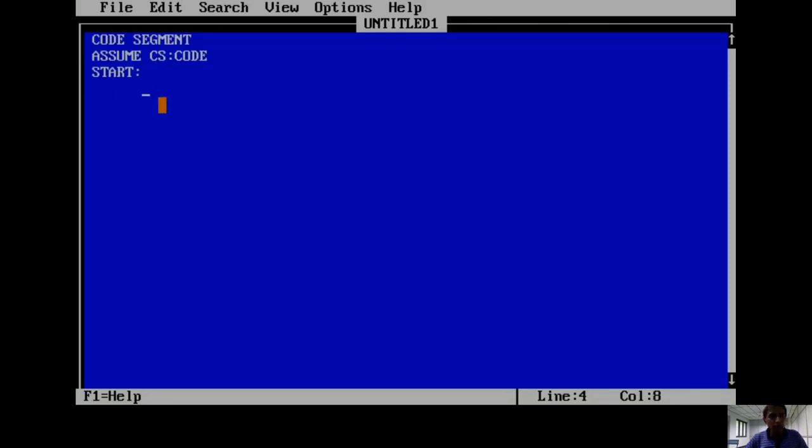Okay, coming to the next instructions, these are processor control instructions, and these instructions will generate machine code. Let us see the first one, exclusive OR AX comma AX. Why am I writing an exclusive OR operation? I already mentioned that exclusive OR means only when two inputs are of opposite type is the output 1. Here my source operand and destination operand are both the same register. If you perform an exclusive OR on the same registers, then my destination becomes cleared.